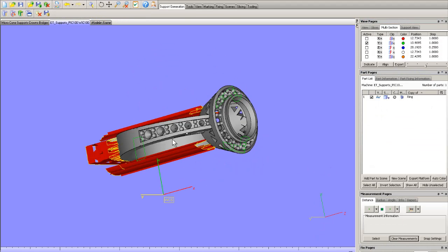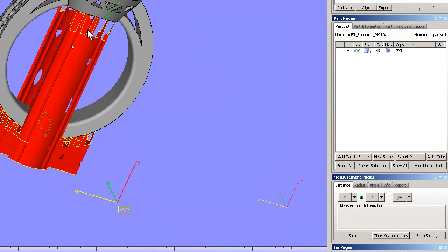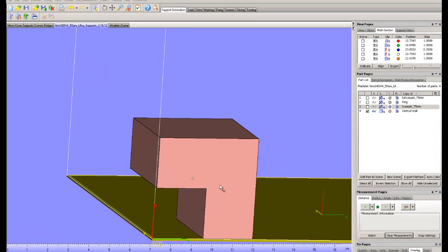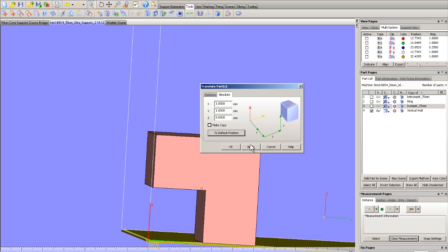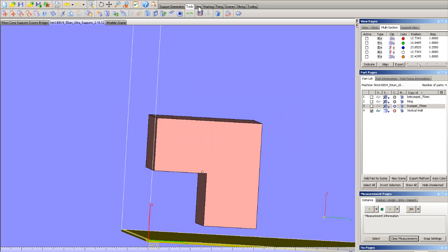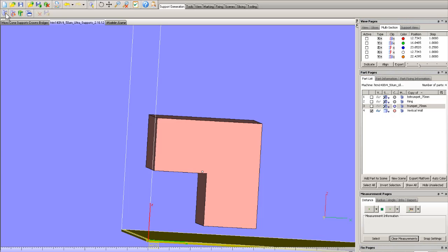At this point, we have the part file, and we have the STL file, and the part file and the support file, and we could actually go down into Perfactory, bring this ring into Perfactory, and build it. But let's bring in another part. I brought in this simple part here, and let's put supports on it. First of all, let's translate it, and then let's go into support it. And we'll take a look at some of our options and how we can change the supports.